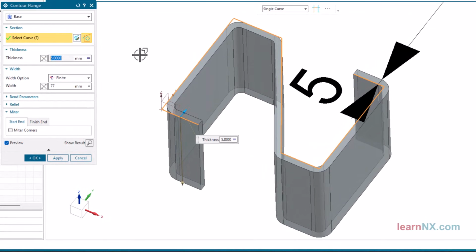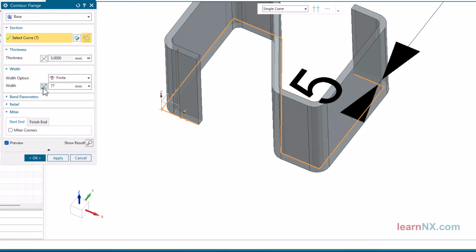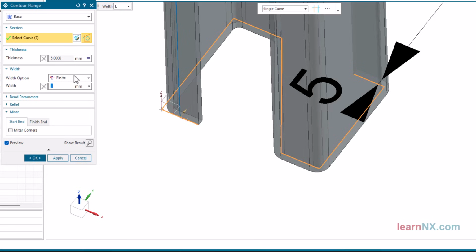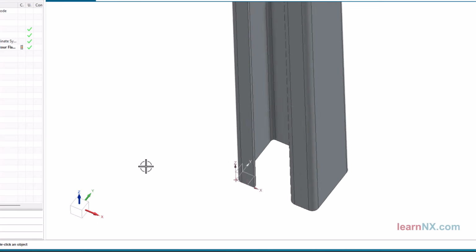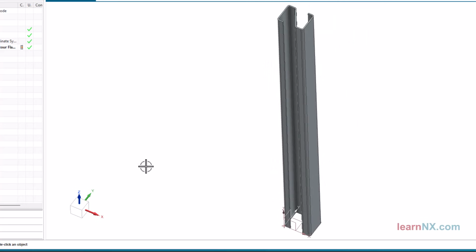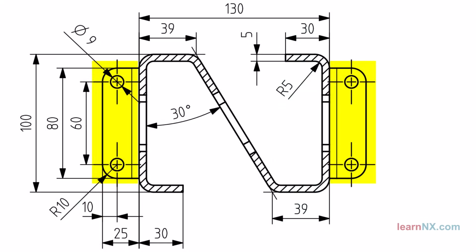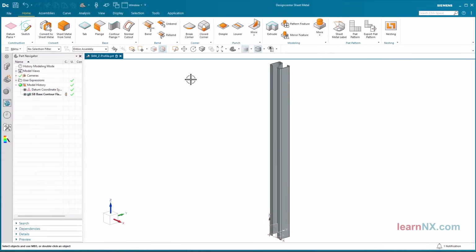Don't just enter the value as the length, enter L equals 1500 instead. This way you have already created the parameter L. The mounting brackets are now added with the flange command. The command was shown in exercise SM2.